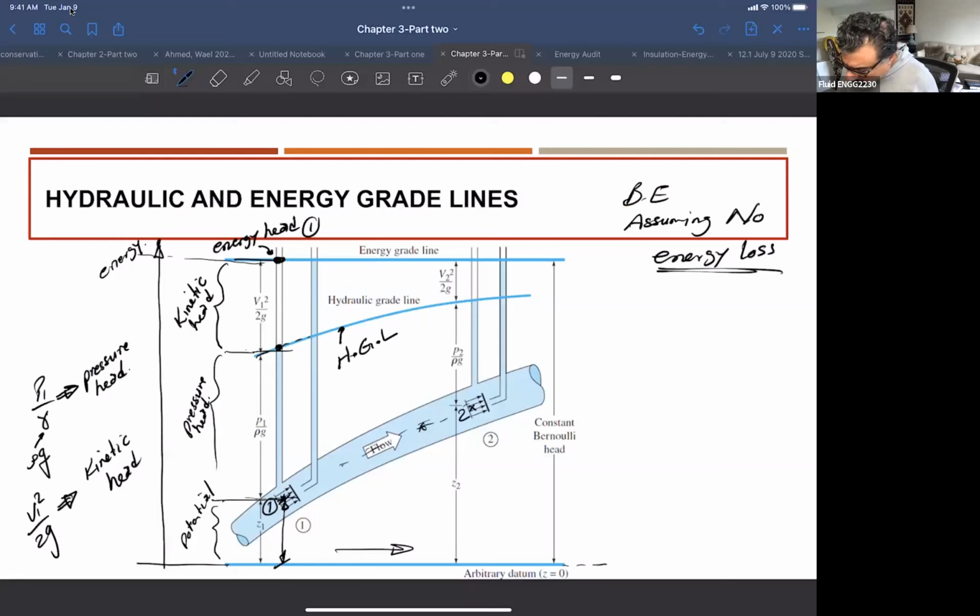Now, if I want to plot the energy line for every single point inside the pipe, it will basically be a horizontal line, okay? So this is the hydraulic gradient line for an ideal flow, and this ideal flow here is referring to the Bernoulli equation at no friction, okay? And basically this is going to be some energy level at the Y scale, okay?